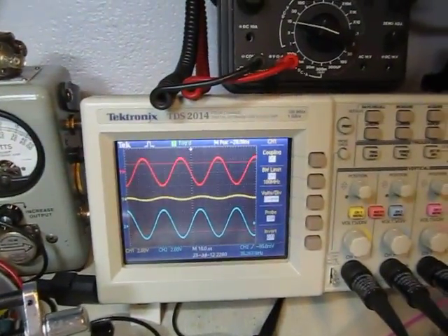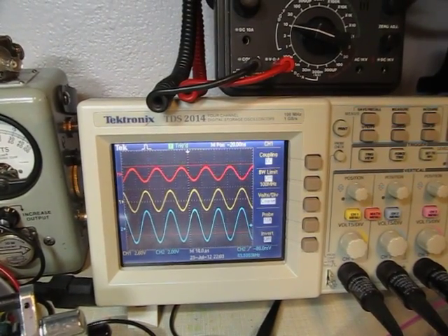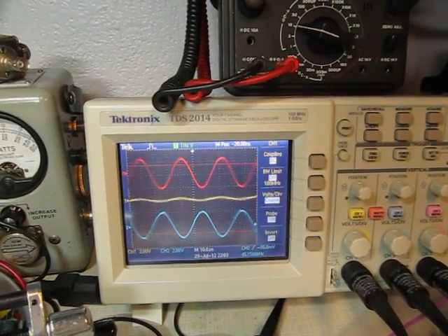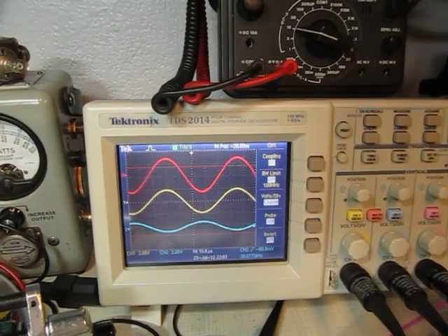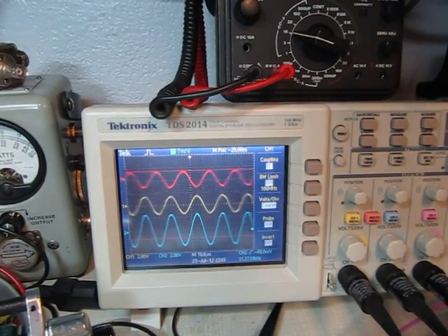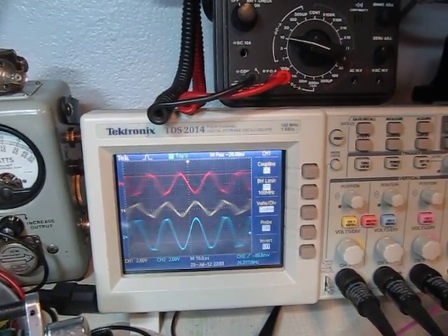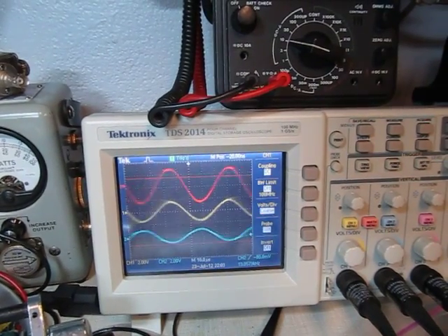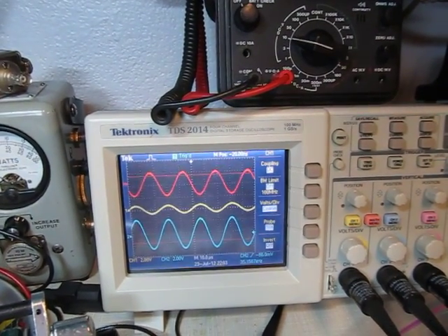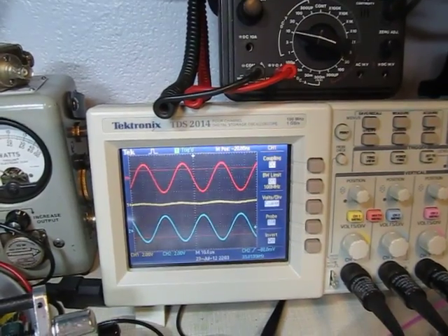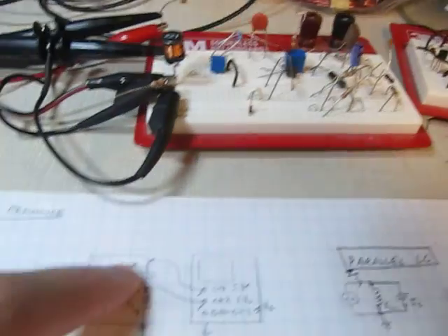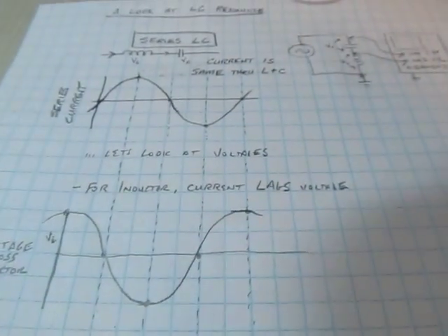And you'll notice as I go below resonance, I get a voltage there. If I go above resonance, I get a voltage. It changes polarity, right? We go from inductive to capacitive and vice versa. Actually, I just said that backwards, but you get the idea. But then as you cross through resonance, you can see that the voltage across this stack goes to 0 because it's essentially been shorted out because of the way these phases add up.